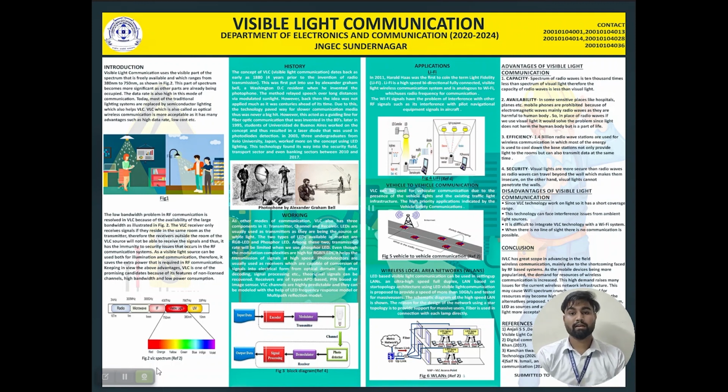Now I shift to longer range. In longer range, we use 4G to 5G communication techniques, which is greater than 1 kilometer. It is the combination of DSRC plus GPS technology. DSRC stands for Dedicated Short Range Communication, which has a frequency of 5 to 5.9 gigahertz. Mainly, V2V communication is used in safety measures like current GPS position, path history, path prediction, and vehicle control information like braking status and steering wheel angle.